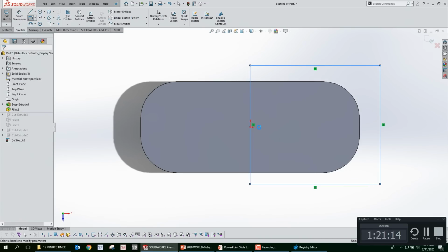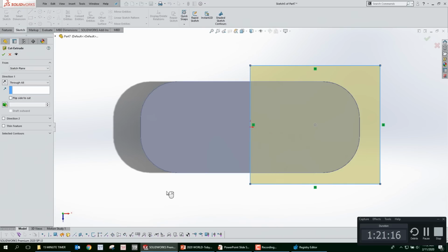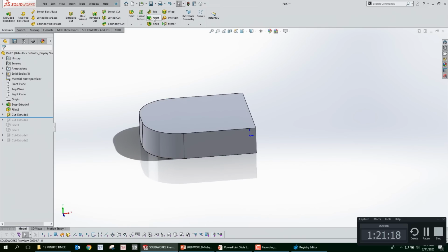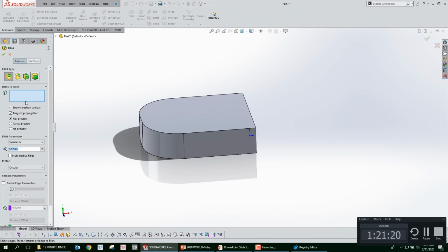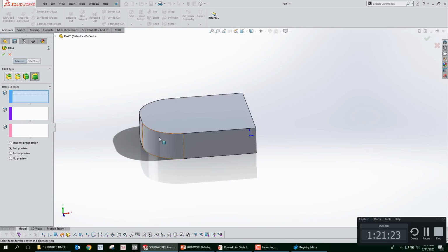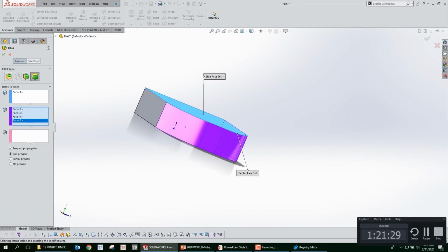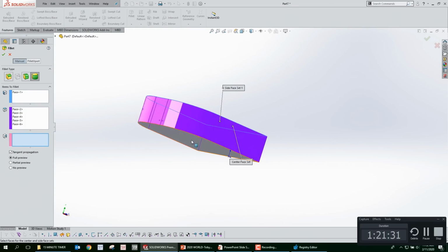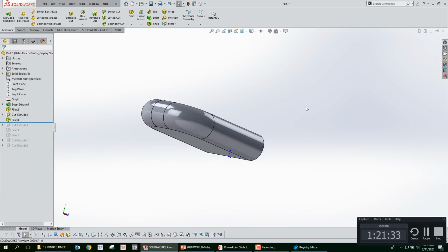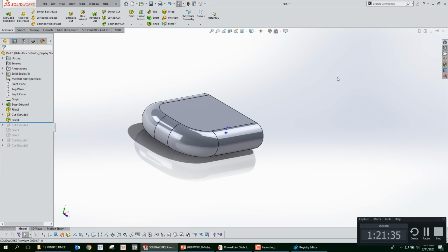So we'll do an extrude cut here. I could have done that a lot more elegantly. And then we're going to go to the full round fillet command. And maybe these faces have draft, whatever, it doesn't matter. So you could do front, and then you could do this, and then you could do this. I know that this is all one face here, but yeah, it'll work. I've done it before. And it could even have varying wall thickness, so if it drafts down, as long as they're tangent, you'll be fine.